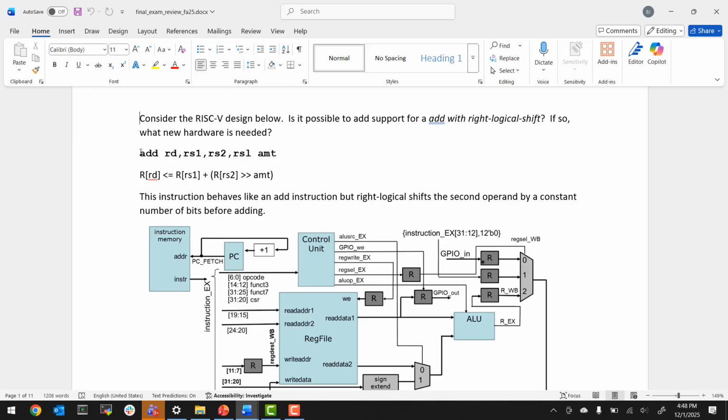You remember the fixed point stuff we did earlier, where when you multiply 2 fixed point numbers, the number of fractional bits increases compared to the inputs, right? If you multiply 2 numbers with 4 fractional bits, the result will have 8 fractional bits.